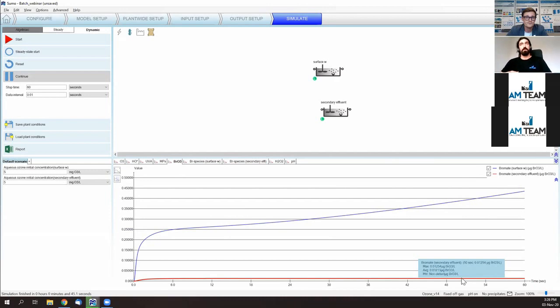You remember what Wim just mentioned about the two ways of starting up the bromate formations that you can have, either way with radicals or with ozone. Well, in the secondary effluent sample, you have limited possibility there because both are being depleted very fast. So this is mainly what is about the difference that we are observing here.